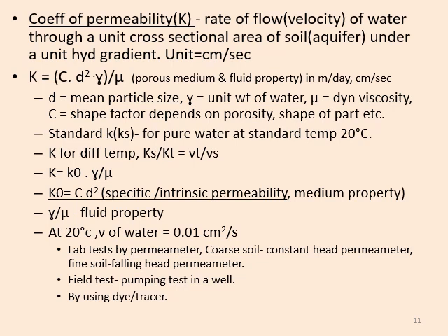K naught is named as specific permeability or intrinsic permeability. It only depends on the medium property, meaning the aquifer medium property. C is shape factor and d is the mean particle size of that aquifer.